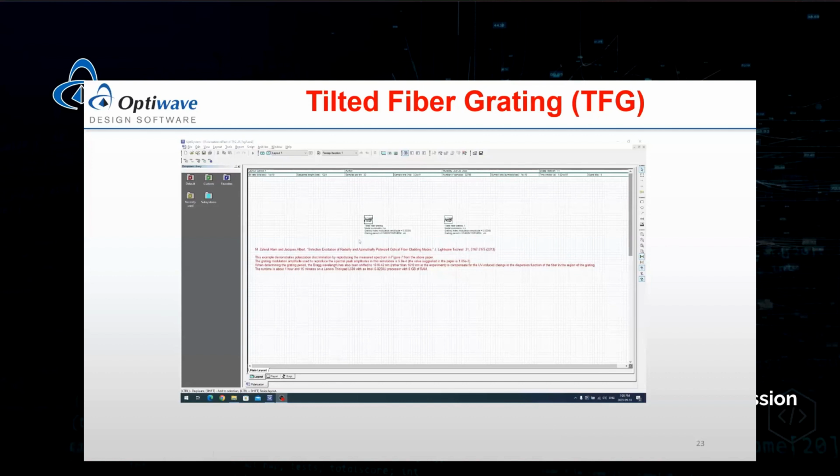Firstly, this component is able to simulate full vector modes for fibers with an arbitrary number of layers, whereas OptiGrating is limited to 2 layers for full vector mode simulations. Secondly, this component is able to distinguish between perpendicular and parallel polarization when evaluating these spectra, whereas OptiGrating is limited to perpendicular polarization only. Lastly, this component is capable of simulating radiation modes, whereas OptiGrating cannot.